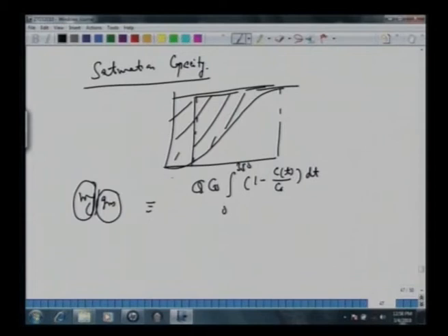Essentially, this area under the curve, either you solve numerically, since you know all these data points, making use of certain numerical methods to calculate this area, or even approximately one can measure, assuming that's rectangular, maybe this is very close to the triangle, so half length into height here, divided by the total amount of adsorbent. So all this quantity we know, this Q is 80 cc per second. This C0 we know, how much ppm we have.